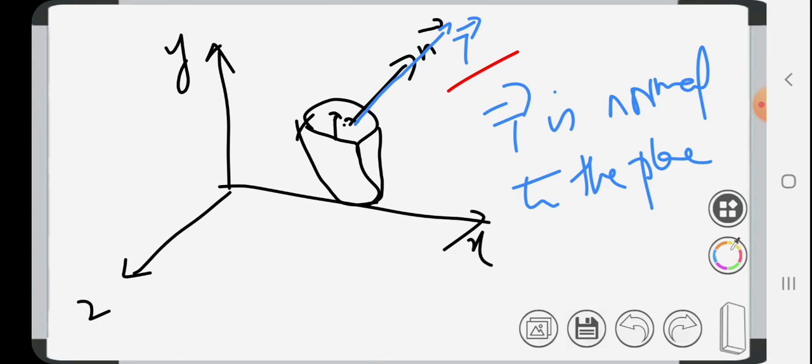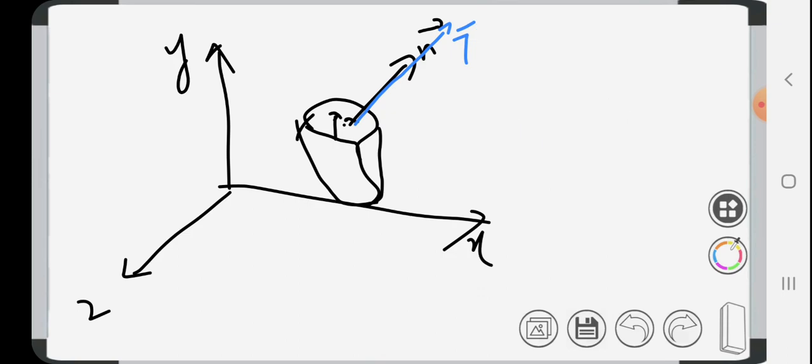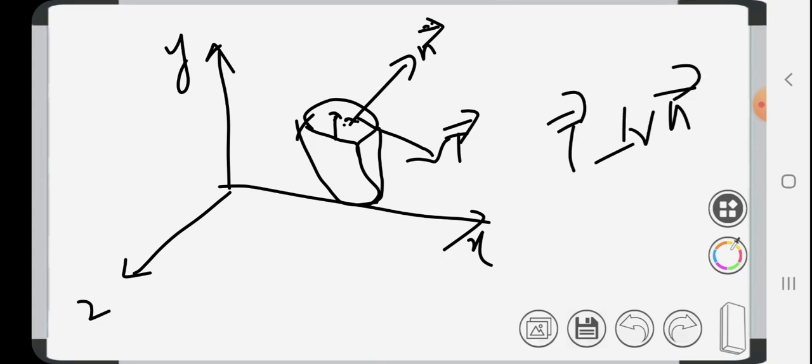That's another question. There may be some plane where the tangential or shear stress is maximum. The t vector is wholly tangential, or perpendicular to the normal vector. So here no normal component, only a shear component, and the shear component is maximum.